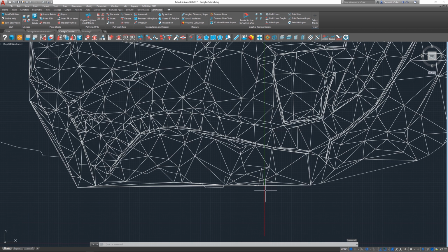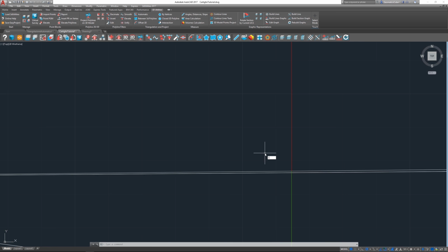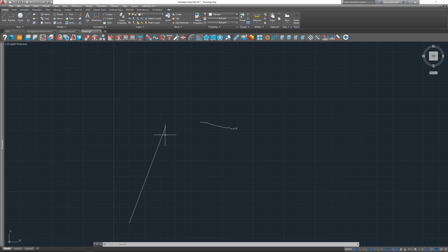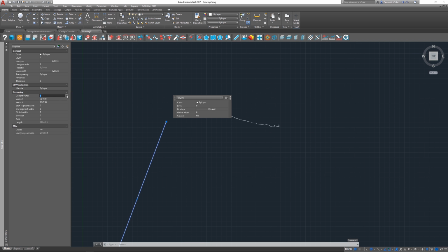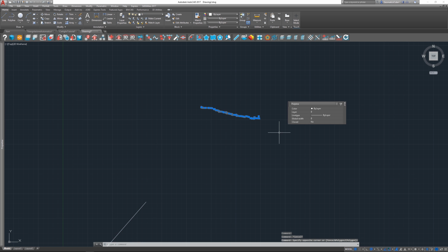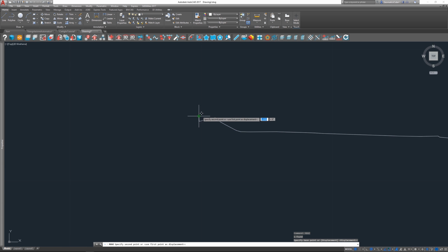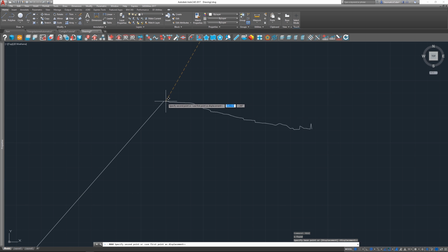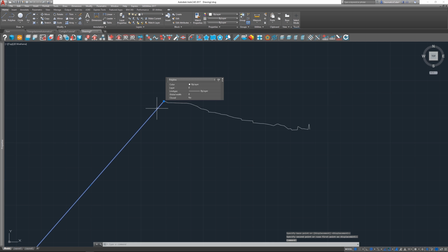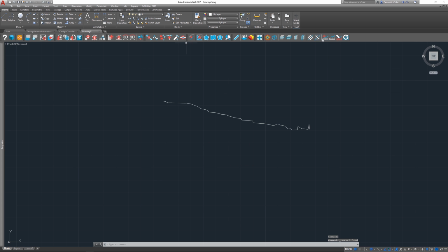So back here, I'm going to make an EV of this point, just like this, and I'm going to take this EV, and as you can see, the elevation is 233. I'm drawing a new polyline, and I'm going to specify on the Y vertex the same value, 233.4031. I'm selecting the polyline, and I'm going to move it in the correct position. So by using move, I'm going to move it right here. So now my Y value is actually the correct elevation.